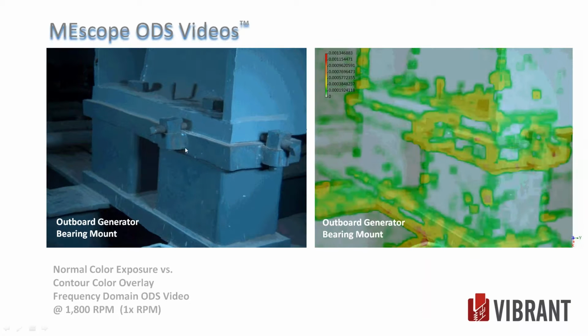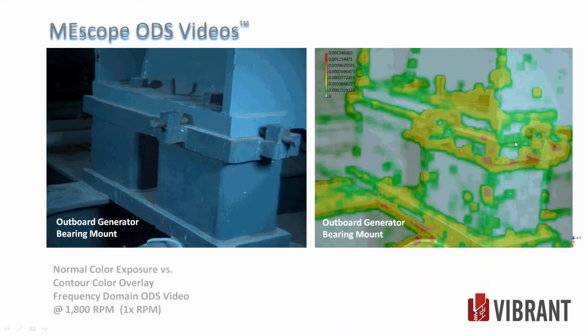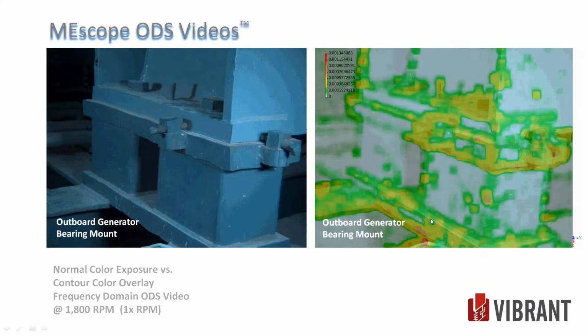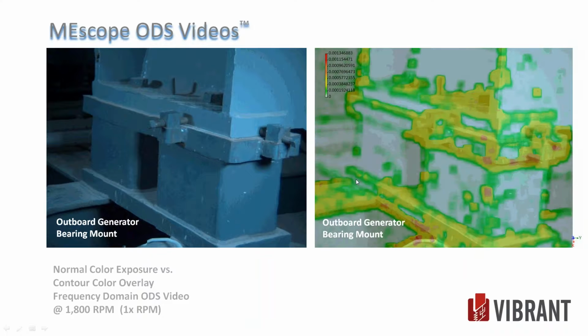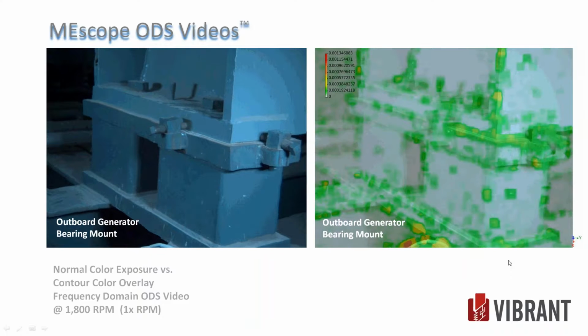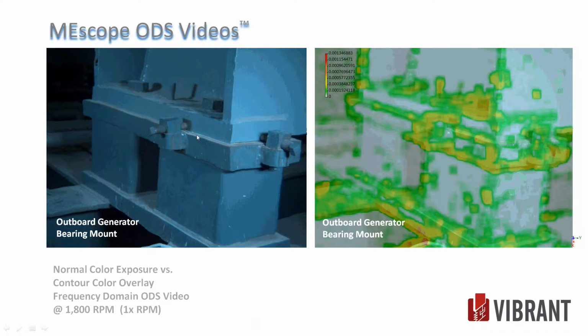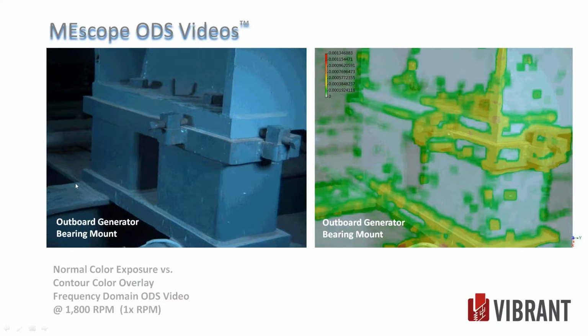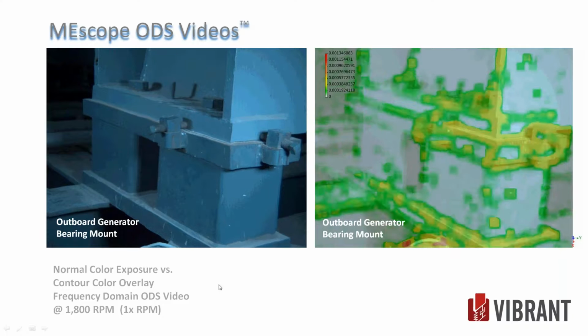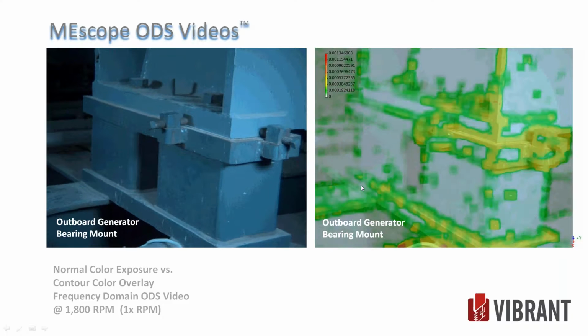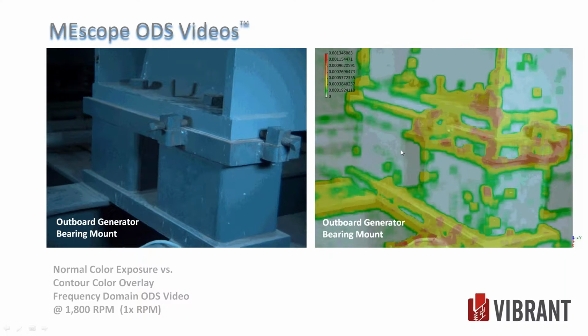We checked it out. So this is one of those mounts. We did all 4 of them. We couldn't find anything. Everything was moving together. There was no out of phase motion. Okay, so we couldn't find a shim improper. We couldn't find a crack in any I-beam supporting the structure, but still the floor was shaking, about 2 or 3 times higher than what it should be.